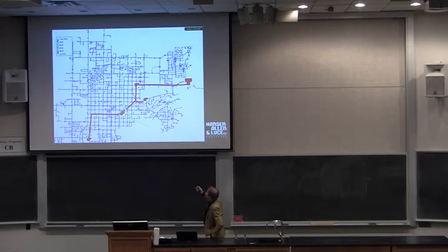But in the end, what we convinced them of is to create a pressure zone to reduce the pressure down here, and then reduce the heads of these wells, which automatically is an energy savings. And we'll take that water directly to that pressure zone, thereby saving energy and eliminating the need to deliver the water all the way up here and letting it come down at peak or rush hour. So you can think of pipes as roads. There was a lot of competition at a certain time, so they thought they were running out of capacity.